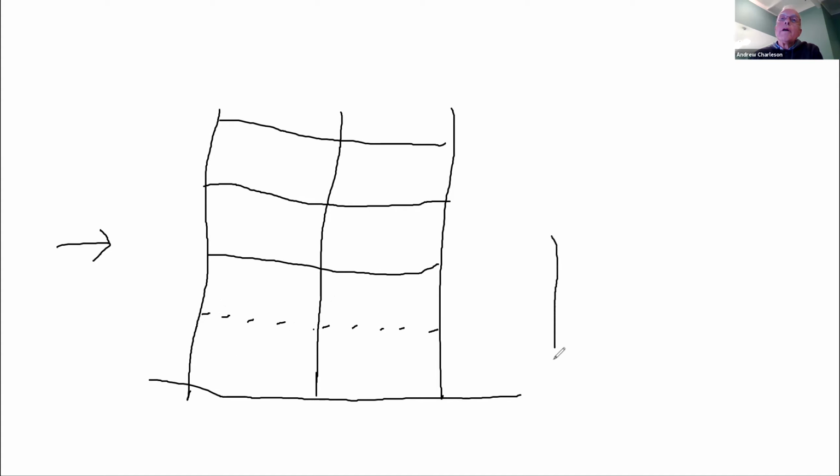And so in plan, you will put, say, a shear wall there in the X direction, a shear wall there, a shear wall here in the Y direction, and maybe a shear wall there in the Y direction.